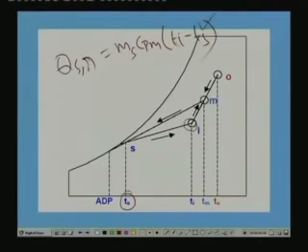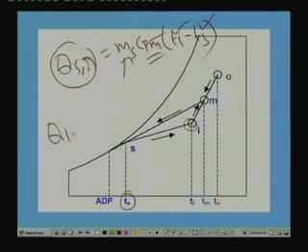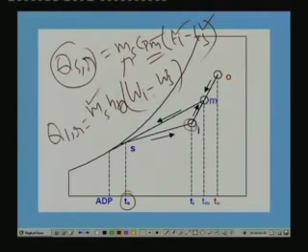So, Ts is specified, Ti is known to us, CPM is known to us, so you can find out what is Ms. Similarly, we have seen the other equation, latent heat load is HFG into (Wi minus Ws). So, Ms is calculated, HFG is known to us, so Ws can be obtained. So, you can fix this condition also.